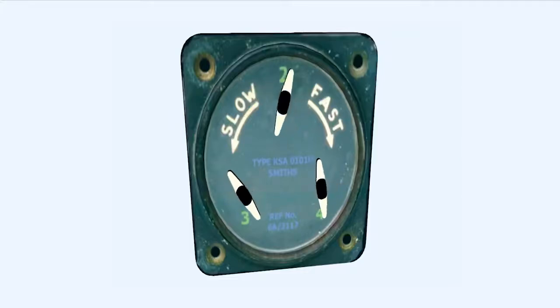Many multi-engined aircraft are provided with a visual indicator, which is called a synchroscope, which indicates the RPM differences between the slave engines and the master. As you can see from this picture, the presentation consists of miniature propellers, which rotate to show when an RPM difference exists and whether the slave is faster or slower than the master.